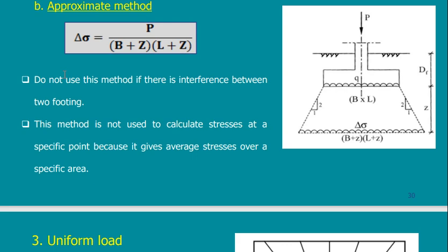You never go vertically with your load except if the shear strength of the soil is 0. When you stand in water, you just go vertically down. Why? Because there is no shear in water. But when you stand on soil, you don't go vertically down. Why? Because the friction and the shear between the soil particles prevent you from falling down. So what happens is that your load is dispersed at a bigger distance below, and once it is spread below, it affects a bigger area.